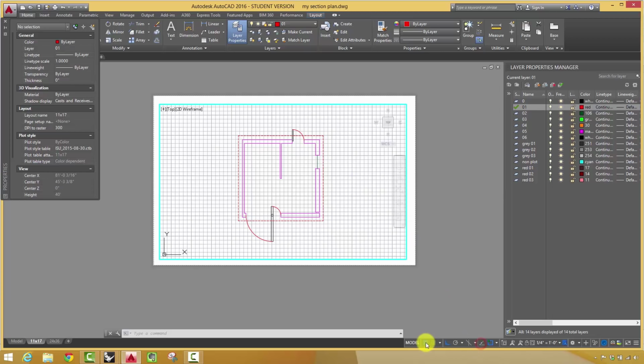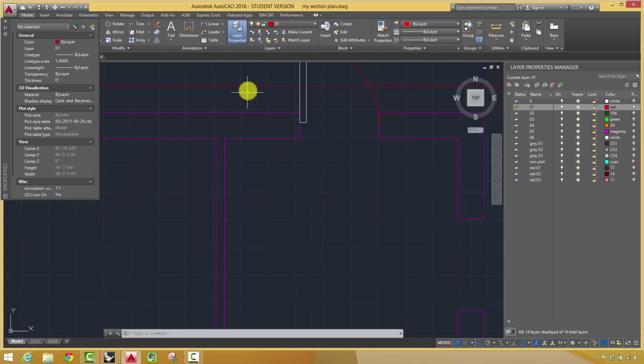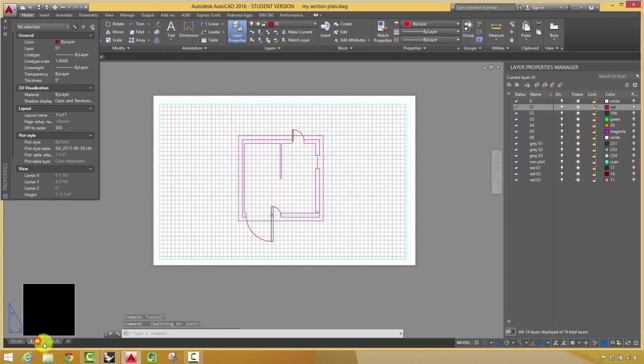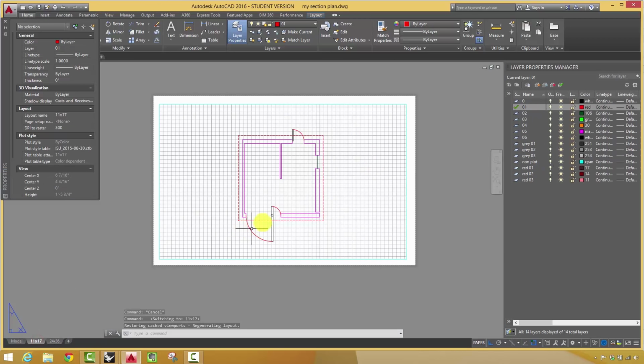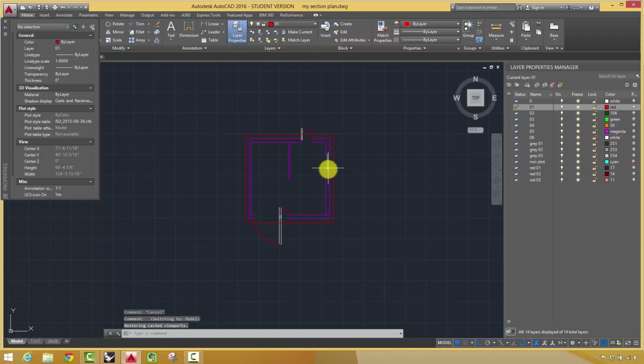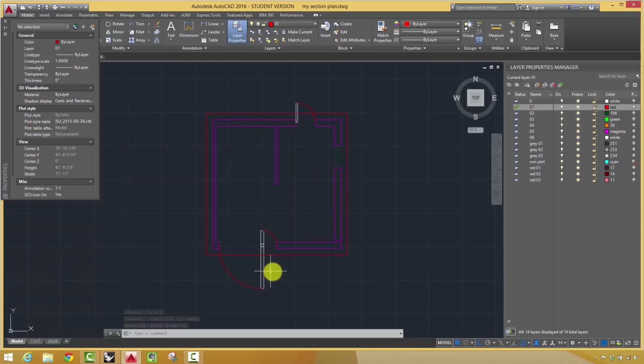Okay. So when I go back to my drawing, you can't really read the scale here, but it doesn't matter because it's actually the scale that it plots at that matters. So again, just to show, when I go into the layout, I can change the line type, and then I can change the line type scale, and that's going to help this thing read a little bit better. Okay, and then let's see the other piece that I want. So for this drawing,